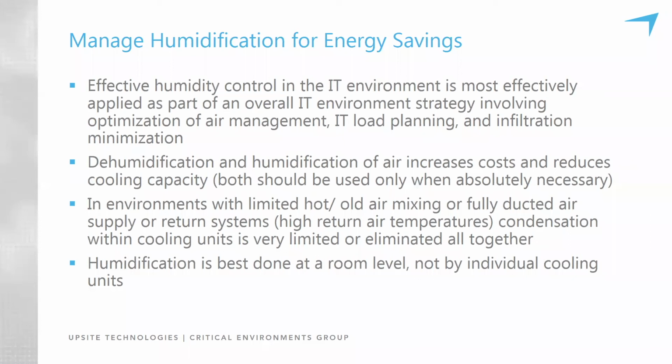Humidification control in the computer room is another very important aspect of saving money. Humidity control is most effective when it's applied as part of an overall strategy. It's most effective when humidification and dehumidification control is done from a centralized location, and all the humidification and dehumidification functionality in the individual cooling units is turned off.